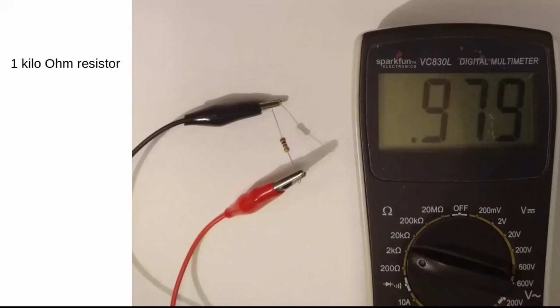Next, this is a device known as a resistor, and we'll get into components in the next lecture. But this is what provides resistance in electrical circuitry. In this case, it's a 1 kiloohm resistor, and the multimeter is reading 0.979 kiloohms. So we can safely round this off to 1 kiloohm.